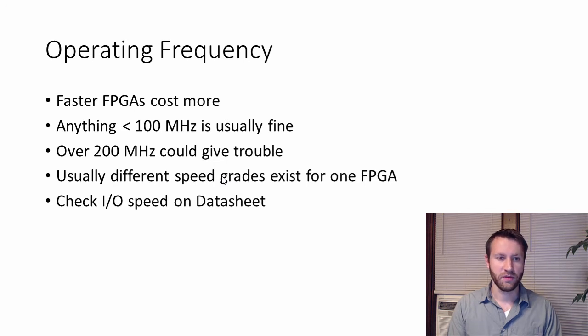One thing I was saying before was that you can always buy the fastest speed grade, the one with the highest registers and flip-flops, and you can always go down. So you can always start with like a -3 in one particular package and then go to a -1, and that might be fast enough for your design. The -1s usually cost less.